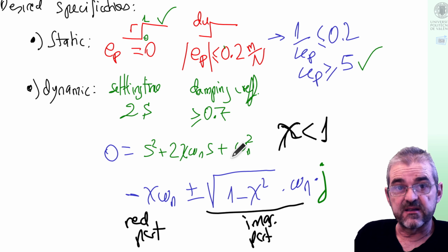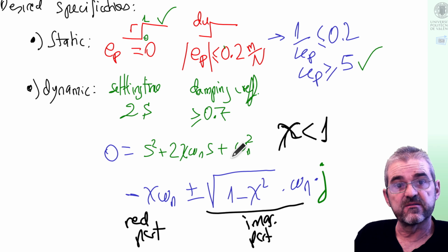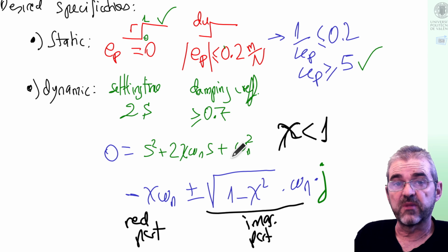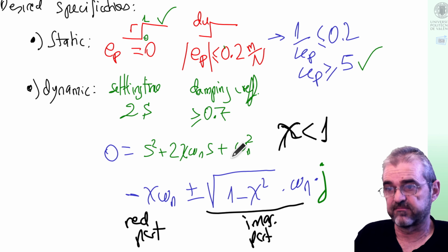As we are happy with chi equal to 0.7, we will indeed set chi to 0.7, because the more damping I wish, the stronger the damping in our mechanical analogy will need to be, the higher the derivative gain, and derivative gains have the problem of high frequency noise amplification. So usually in control design, one does not make the gains higher than the minimum required, because higher gains mean higher likelihood of saturation and higher noise amplification. So we will decide a damping of exactly 0.7.